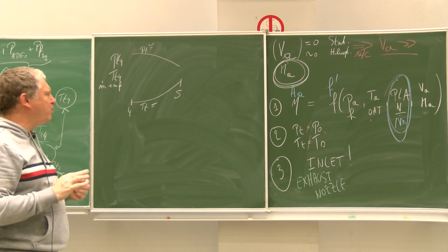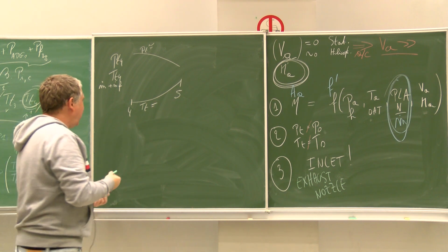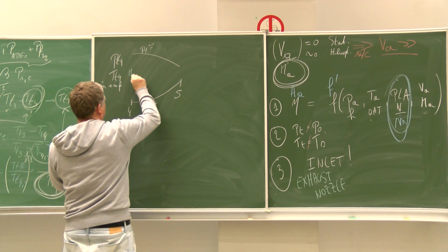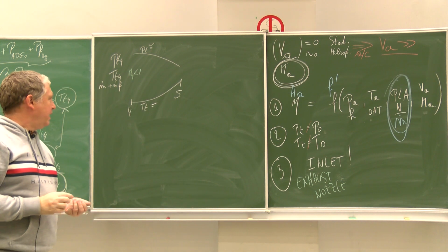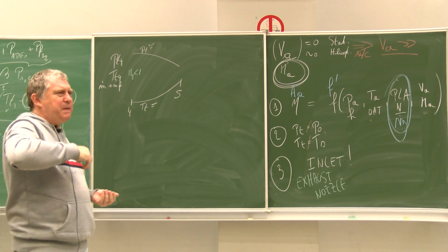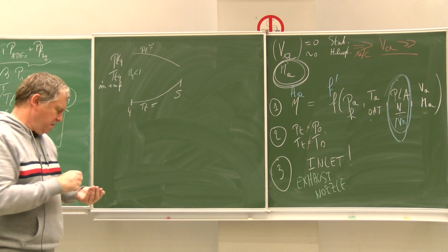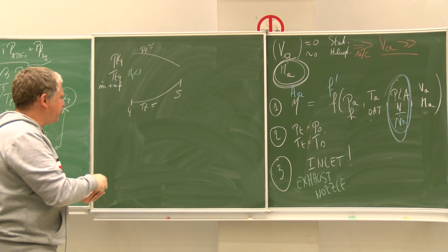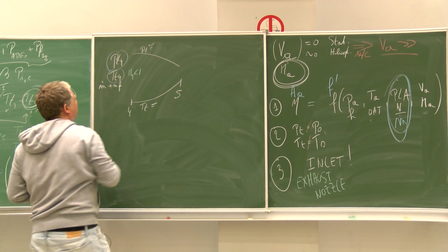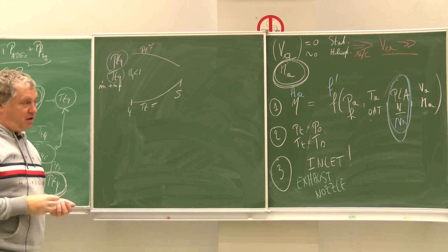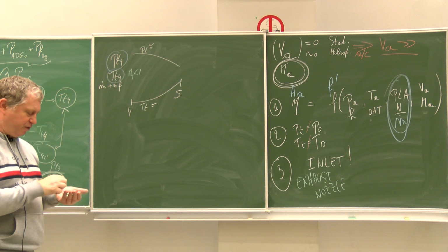It's very easy to implement, but it's not necessary to do. And what's happening? I have a subsonic flow. M4 is for sure lower than 1. And M4 is maybe known by experiments or maybe not known. It's not changing too much the situation because what I will need is just to know the total pressure that I have computed and the total temperature, the real one that I have computed.